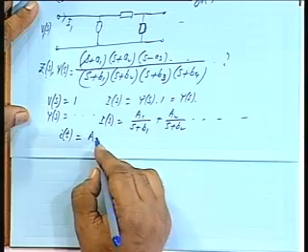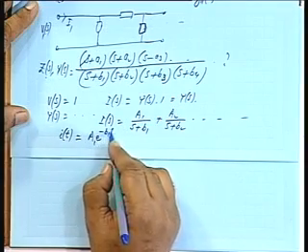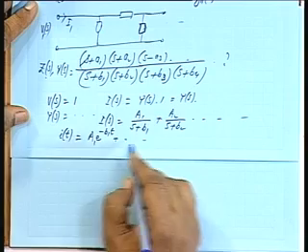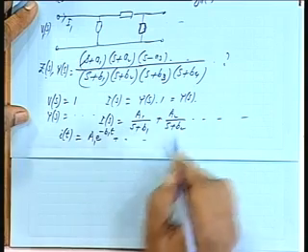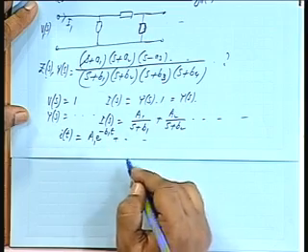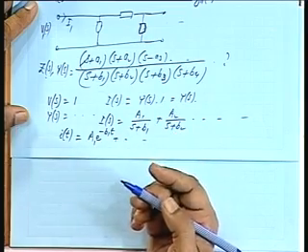It will be A1 into e to the power minus b1t and so on, exponentially decaying terms. Had I had minus b1 term or minus b2, then it will be e to the power plus b1t or b2t. That means the current will exponentially increase. Is it possible physically to get a current by applying just an impulse voltage? You just apply a voltage and withdraw it. Can you have a situation where the current will continuously flow through that and it will keep on increasing?